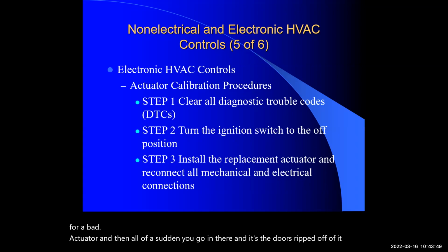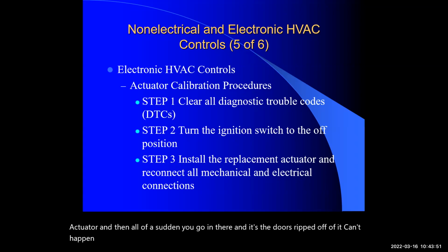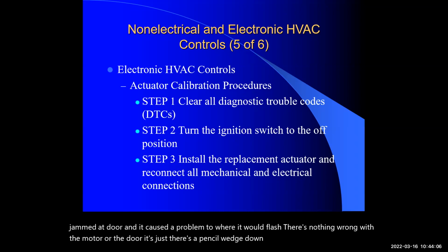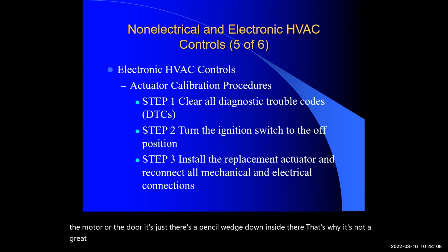It can happen, and I've seen some things too, folks, where a pencil got down inside and jammed that door, and it caused a problem where it would flash. There's nothing wrong with the motor or the door. It's just a pencil wedged down inside there. That's why it's not a great idea to have a bunch of debris, like pencils and stuff, up on your dash.